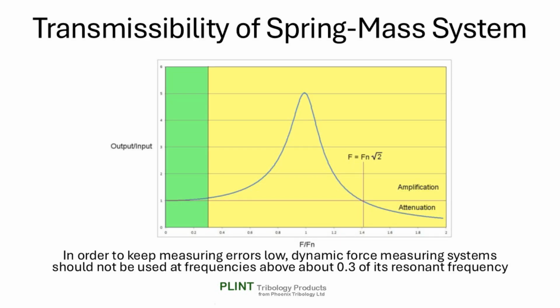The transfer function of a measuring system is the ratio of the output of the system to the input of the system. The transfer functions of measuring systems for load or friction in a tribological experiment are rarely analysed or specified. The closer the excitation frequency gets to the natural frequency, the greater the measurement error, with the output signal considerably amplified with respect to the input signal.